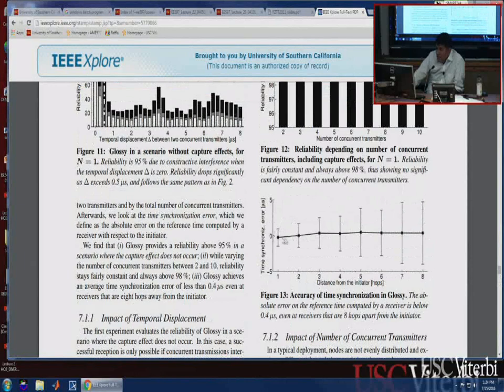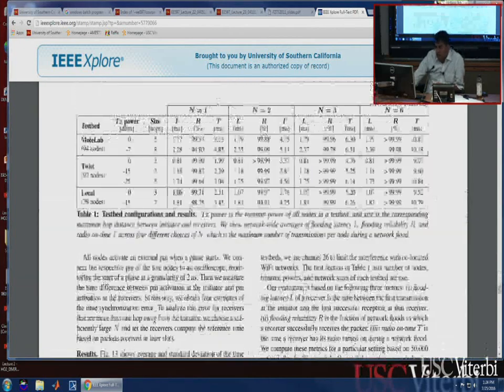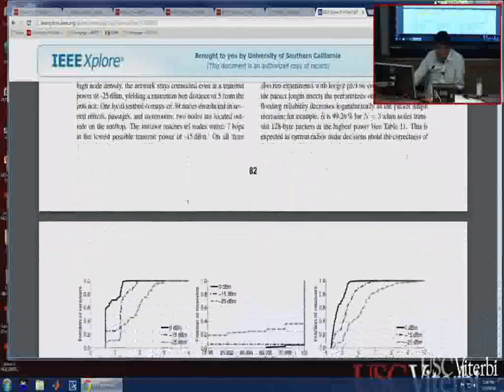reliability. The synchronization error they're able to achieve, so what they do is while they're flooding the packets themselves contain timing information. So the very act of doing this cooperative broadcast is also helping them synchronize the network. And so the source node embeds the local timestamp that gets disseminated to everyone. And part of their protocol is to make every node in the network synchronized with the broadcaster. And that allows them to also maintain very low synchronization error, so it sort of feeds off of itself.